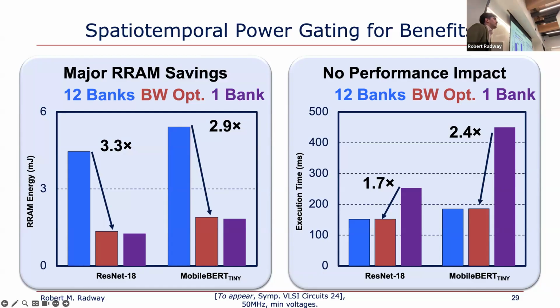Yeah, so if you have something that requires lots of writing, like training, RRAM is not the best. RRAM is very expensive to write to, but it's cheap to read. So for inferencing, it's very good, but for anything that's online training, you have to come up with new algorithmic approaches, which I'll briefly mention. In general, though, if you have models that have this high dynamic range of bandwidth requirements, RRAM is very, very good if you do this implementation. So transformers, CNNs, actually most ML models have this, except for dense networks that are uniformly dense.